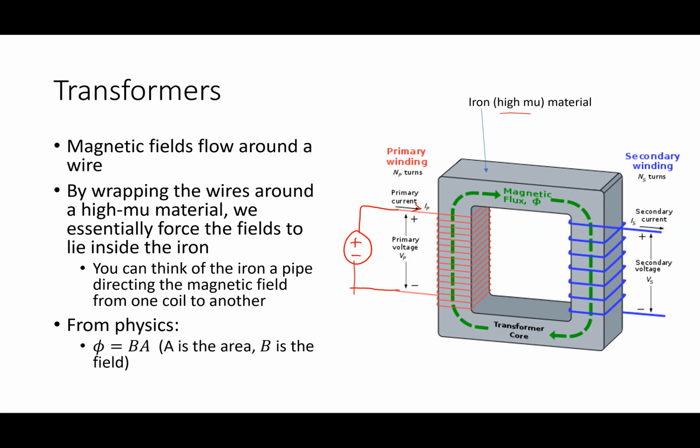Okay. So I have another physics question, going back to the loops. Isn't there also a way, instead of using iron, to take the secondary and rotate it over its horizontal axis over the primary coil to try and get more field? Or is that something that would work? I could take the secondary coil and put it directly over top of the primary coil, and that would have pretty good coupling. But I really need to have the iron to make sure that none of it leaks out.